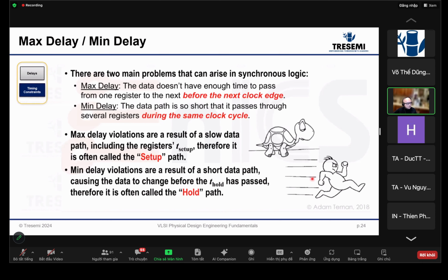So basically, setup and hold are really two corners. One is for the max delay corner, and one is the min delay corner. This will become obvious when you go through a couple of STA examples. Because the signal has to be fast enough to arrive before the clock edge, the maximum delay has to be small enough; if it is smaller than this maximum, you don't have a problem.